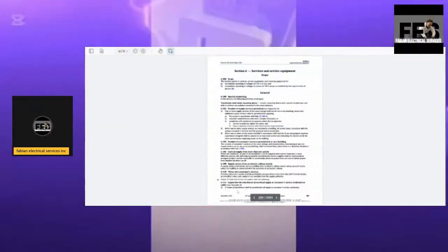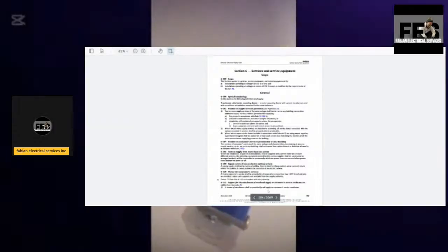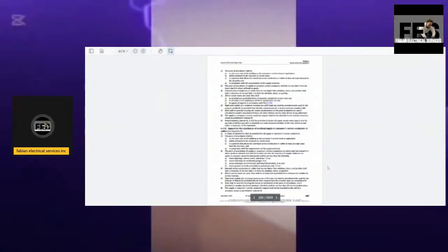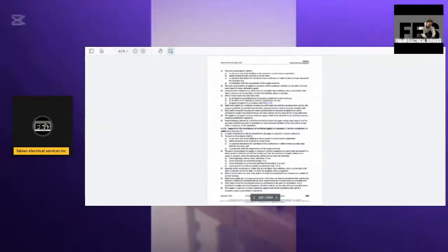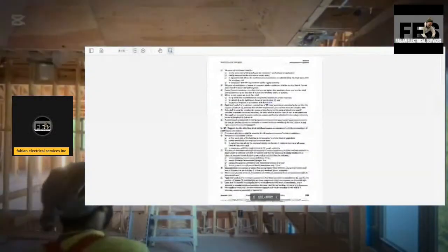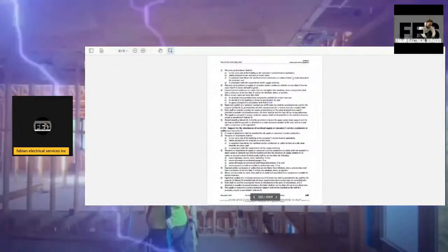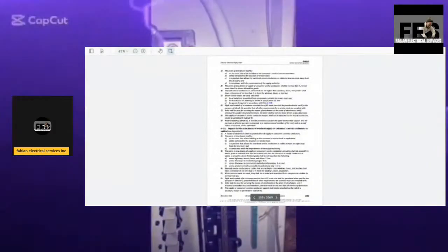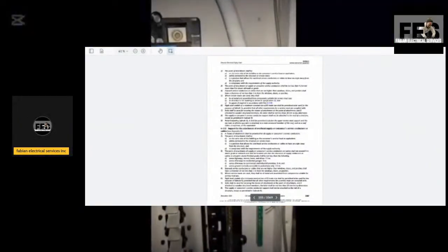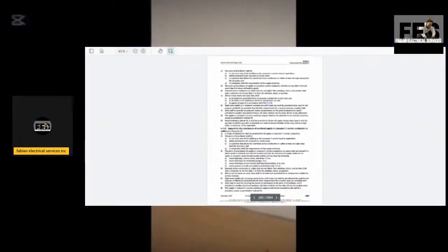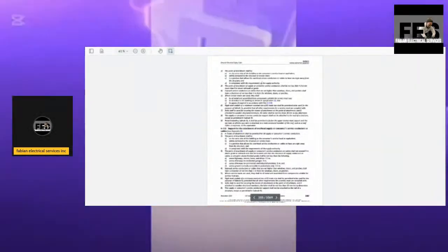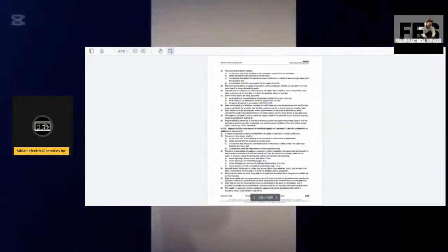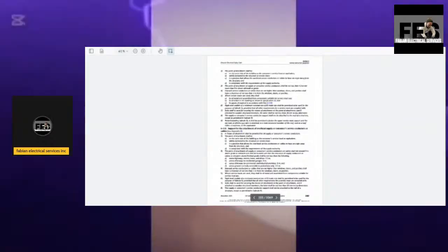A means of attachment shall be provided for all supply or consumer service conductors. The point of attachment shall be on the same side of the building as the consumer service head or equivalent, solidly anchored to the structure or service mast, in a position that allows the overhead service conductors or cables to have an angle away from the structure and in compliance with the requirements of the supply authority.